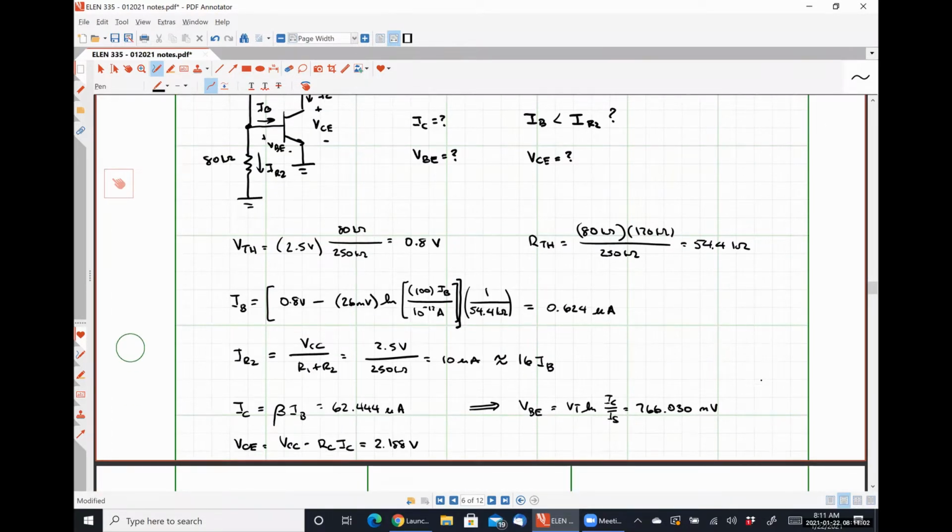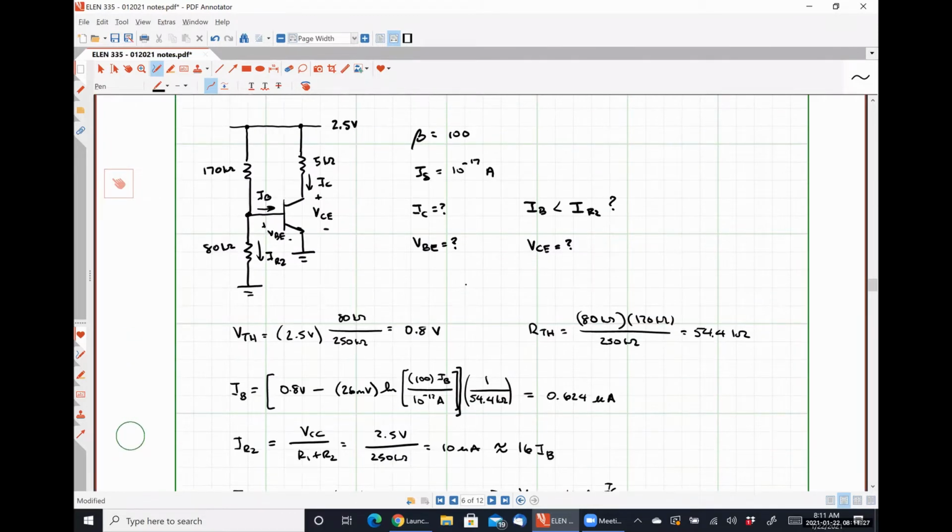So before we move along here, is there any questions regarding this example problem or our resistive biasing techniques? Yes, sir. So the current through R2, we are comparing, it's not the actual current through resistor R2. And what I mean by that is we're assuming what it would be if none of the current branched off. And that's how we're making our comparison.